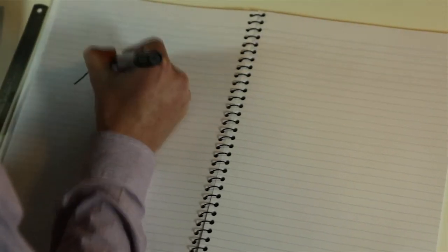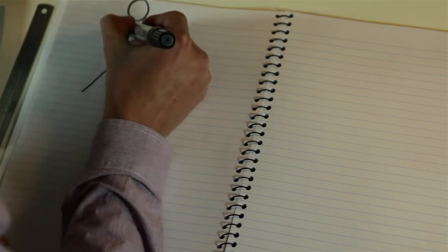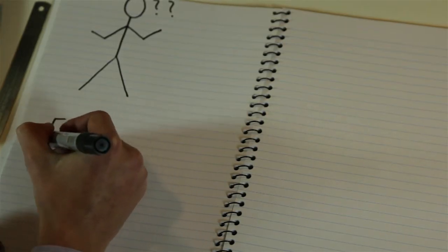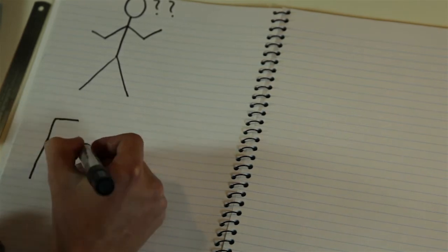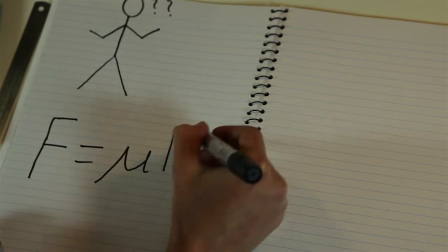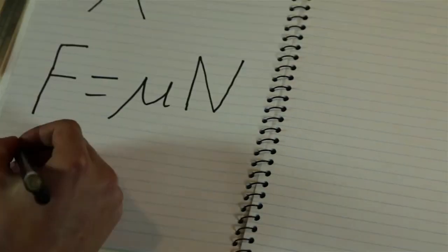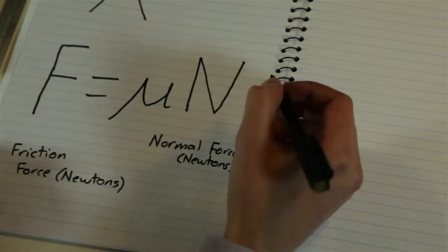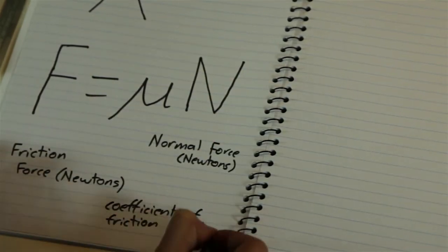We're engineers, so we like quantifying things. How do we work out how much friction there is? Luckily, we have a formula to calculate friction between dry surfaces. F equals mu times N. We multiply the relevant coefficient of friction by the normal force, the force pushing the two surfaces together, acting perpendicular to the surfaces.